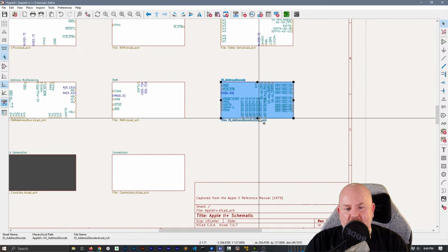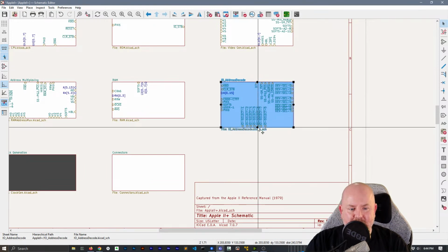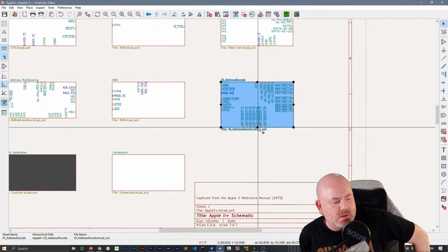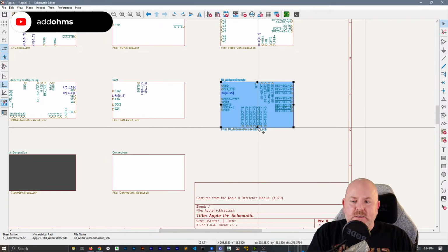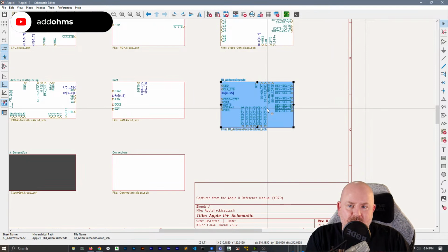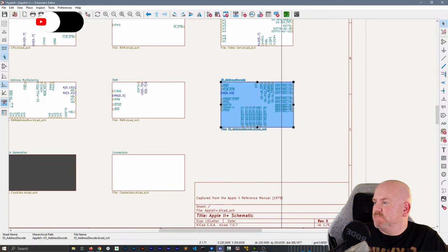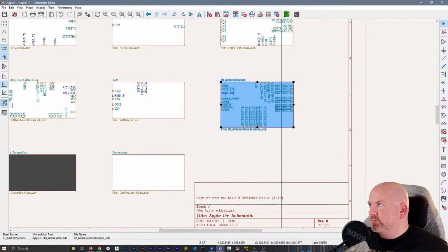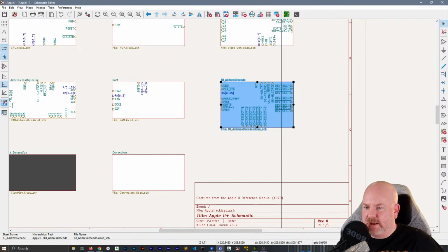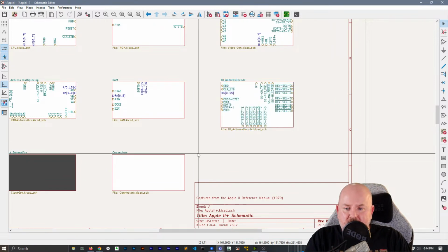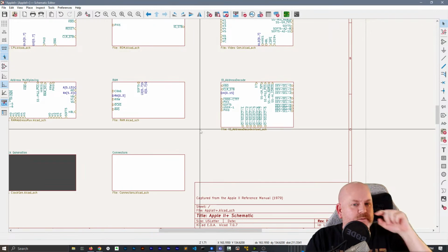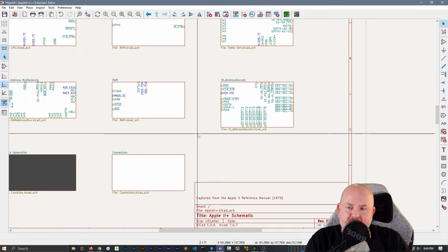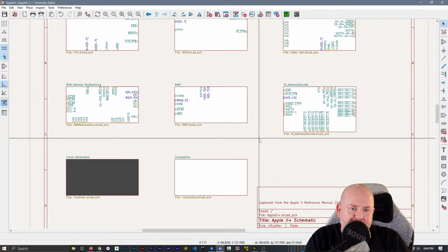The biggest mistake they made was they changed the grid, and so they had a funny grid. In KiCad, ideally you want it to be 1.27 millimeter, or an integer divider of that. So I keep mine at 0.635, which is 1.27 divided by 2. Otherwise, you get about 2,000 off-the-grid messages. So it took us a couple weeks to clean all that up.